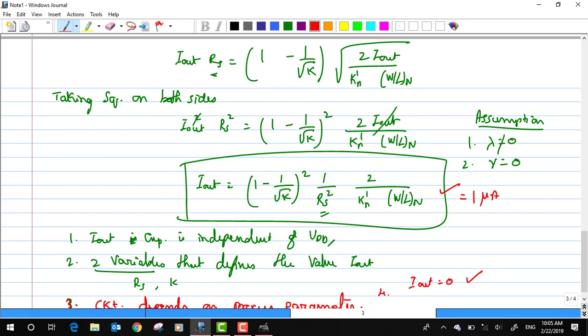So this particular point, when I really turn on the device, the circuit in general gets into this particular operating point, okay, and this operating point we call a degenerate point. And I somehow want to push or drive the circuit out of this degenerate point and switch over to this operating point, okay. So it is something like a monostable, okay. So the stable point is here, or it could be a bistable, because even this is a stable point.